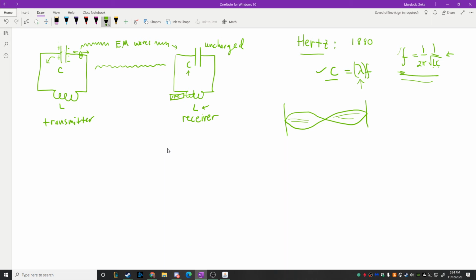At the end of the day, if you think about older radios where you have to tune into a station with a knob, that knob is directly connected to a little piece of iron that's sliding in and out of a solenoid. If you can believe it, that's all that's happening: this little piece of iron is sliding into or out of the solenoid, and it's altering the inductance, which then alters the channel that you're tuned into, right? Does that all make sense?